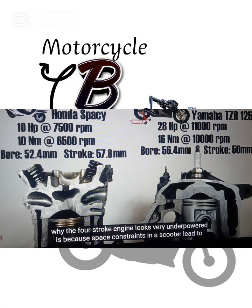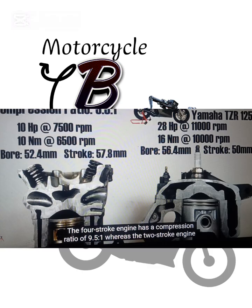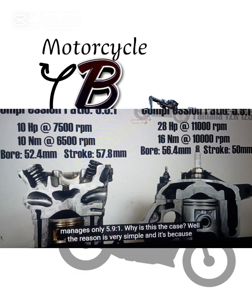One of the reasons why the four-stroke engine looks very underpowered is because space constraints in a scooter lead to restrictive intake and exhaust designs. The other reason is that the scooter engine is focused on economy and user-friendly power, whereas the sport bike engine is focused on building peak power, which it manages to build and hold over only a very narrow part of the top of the power band. Although both engines have similar bore and stroke specs, they have very different compression ratios. The four-stroke engine has a compression ratio of 9.5 to 1, whereas the two-stroke engine manages only 5.9 to 1.